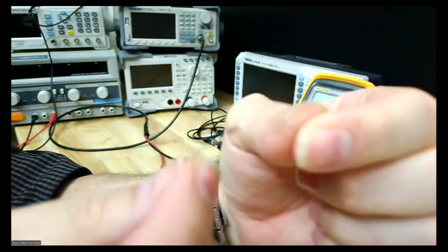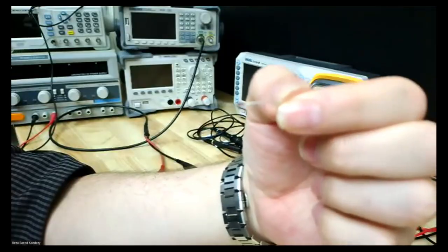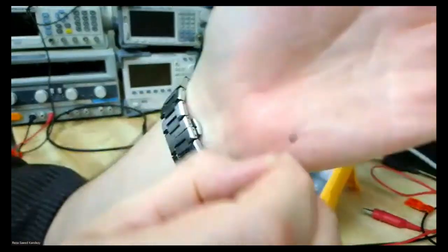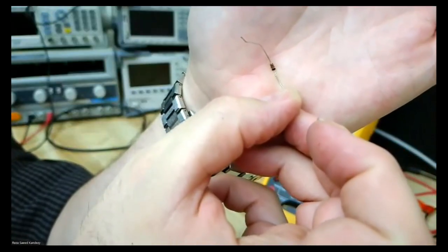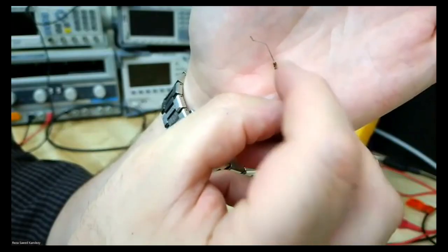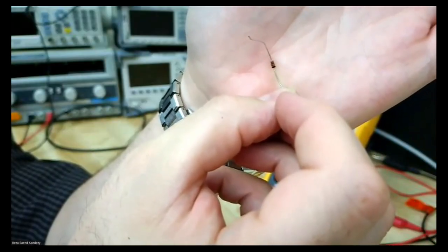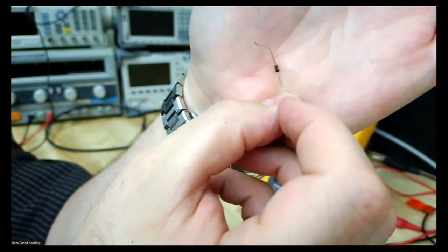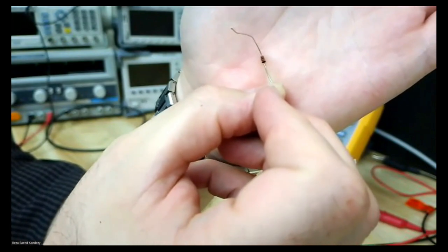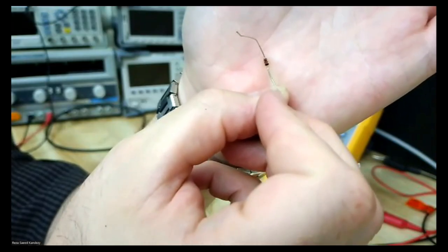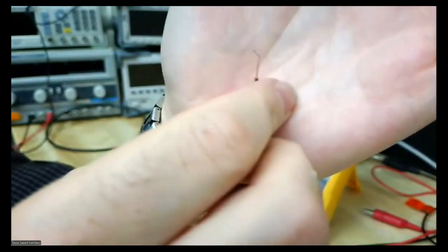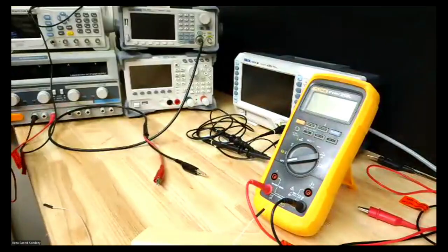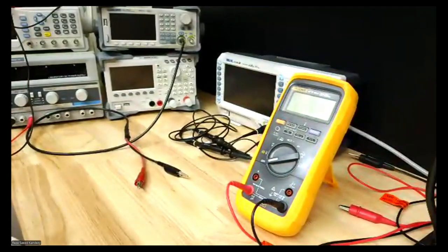We said the diode has an anode... you can see the actual diode. Yeah, the diode has two terminals, anode and cathode. You see one of them has a black band marked on it. That one, like here is the bottom one. That black band means cathode. So the other one is anode. The black one is cathode. Okay, so when you want to do the forward bias, you need to pay attention to those connections.